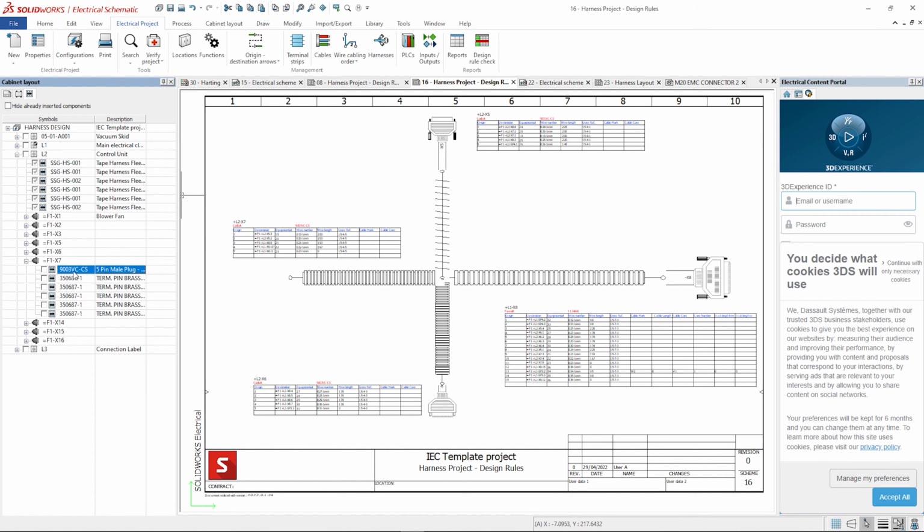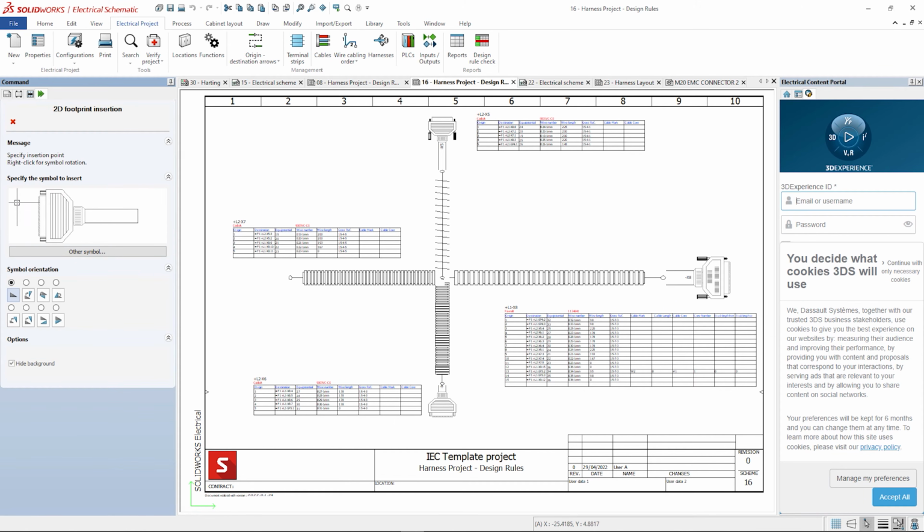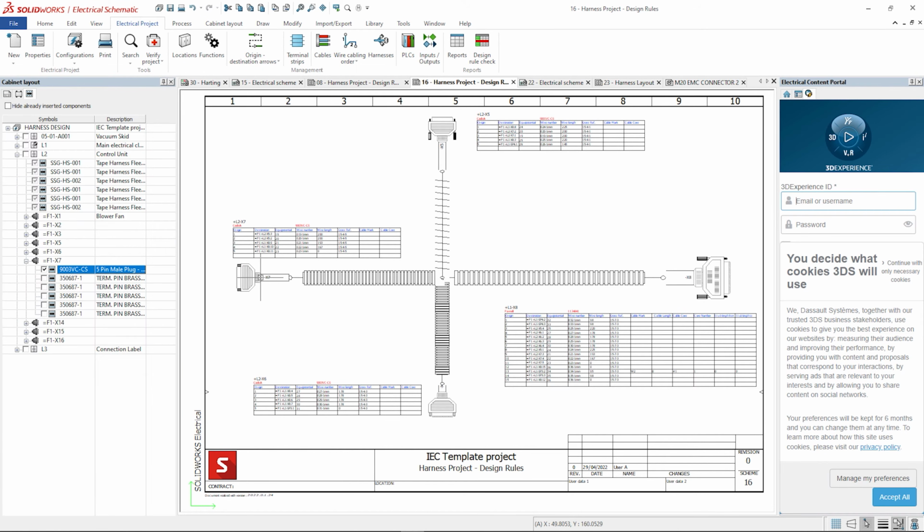All the information will be provided by the library, because each component has a part associated, where we can define what graphical symbol will represent our object. That allows us to click Insert, and as the symbol is already mapped, we can quickly place this element.